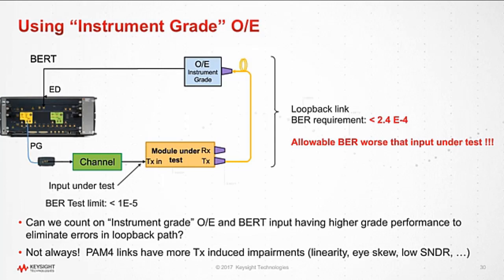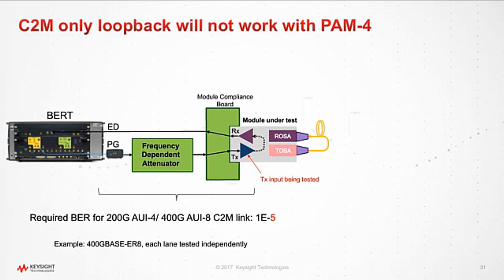So now let's look at another approach. Some of the electronics that we've seen, and this customer that I was working with in Asia, they had this very same problem. And they did have this capability in there. After they tried the optical, they tried the electrical. They have the ability in their interface electronics that drive the TOSA with the host side. Their interface electronics have a test mode that allows a host side loopback. So it takes the TX input signal, and rather than driving the VCSEL driver with it, they wrap that signal around into the received data output, and they retransmit that signal back, okay?